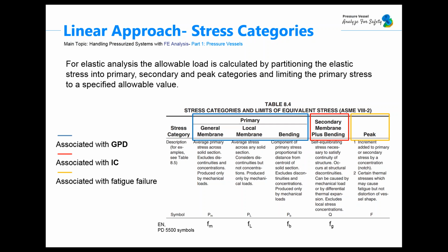And finally, secondary stresses originate through the self-constraint of the structure, and this type of stress must satisfy the imposed strain or displacement as opposed to being in equilibrium with the external load. So this type of stress is called self-limiting. Sometimes you can meet them defined as self-equilibrating, which allows them to exceed yield, since small plastic deformations will redistribute the stresses to other parts of the structure.